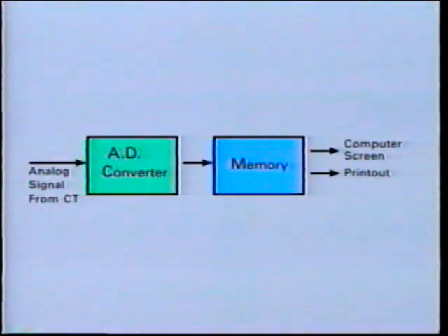This type of system usually allows for a greater number of monitoring inputs. The measurement, that is sampling, is made simultaneously from all inputs, and a very high rate of sampling is achieved, say 6,000 measurements per second. The analog input is converted through an AD converter into a digital signal to be recorded in the memory of the recorder.